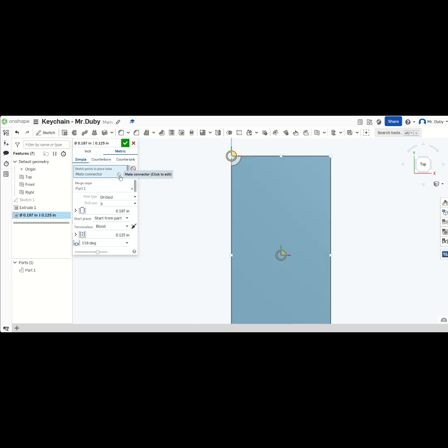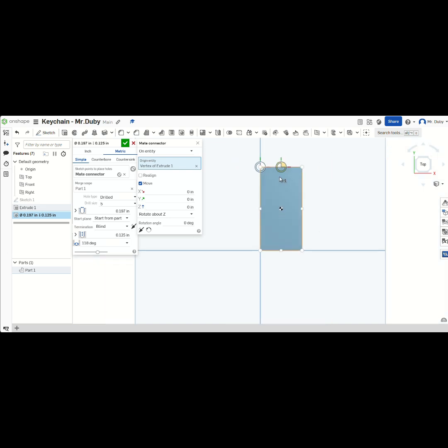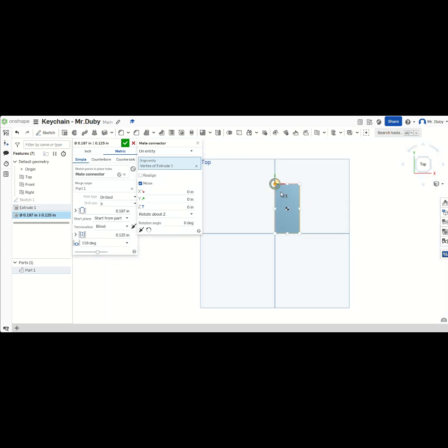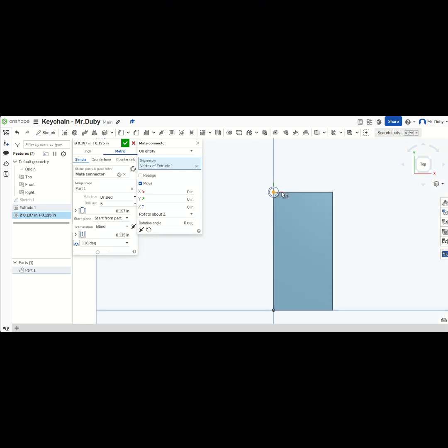So we're going to select this coordinate button, which will allow us to adjust the coordinates in X, Y, or Z. If I zoom out a little bit, you'll notice there's this green line on the top and a red line on the side. That corresponds to the axis that we're looking at. So Y would be in this case our vertical axis, and the X would be our horizontal axis. So we want to move along the X-axis halfway. So we're going to move 0.5. And we want to move along the Y-axis, we want to move down 0.25.